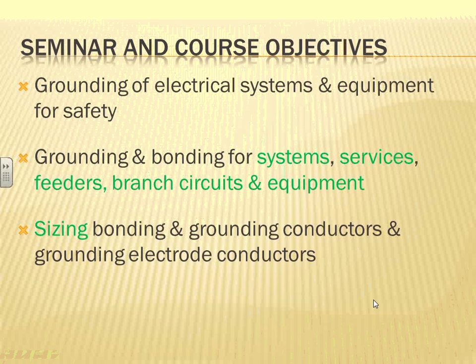One of the most important things, guys, especially for those who have not been around for a while, that confuses people when I start talking about grounding is that there are two very distinct things about grounding. Either you ground the system or you ground the equipment. And these are completely different things. If the system is grounded or ungrounded, meaning you go to the guts of the transformer and take part of the windings and ground it, that's grounding the system, the power system.